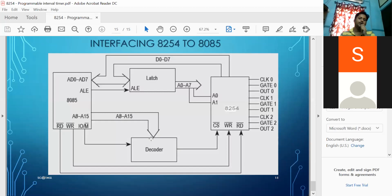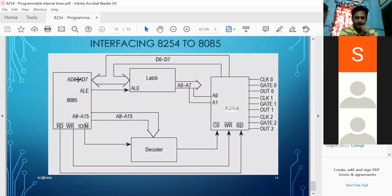And now this is the interfacing circuit by which you can connect an 8085 with the 8254 to operate any delay, or it is used for any timer operation or counter operation. Now here, the lower 8-bit address, AD0 to AD7, is connected via this latch, so that A0 and A1 can be used as your address bits, and D0 to D7 are used as your data bus.